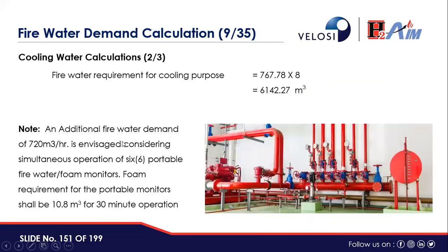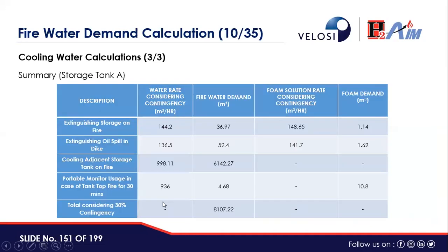So an additional Firewater demand is envisaged considering simultaneous operation of 6 portable Firewater foam monitors. Foam requirement for the portable monitors shall be 10.8 cubic meter for 30-minute operation. So this is the summary for the storage tank A.